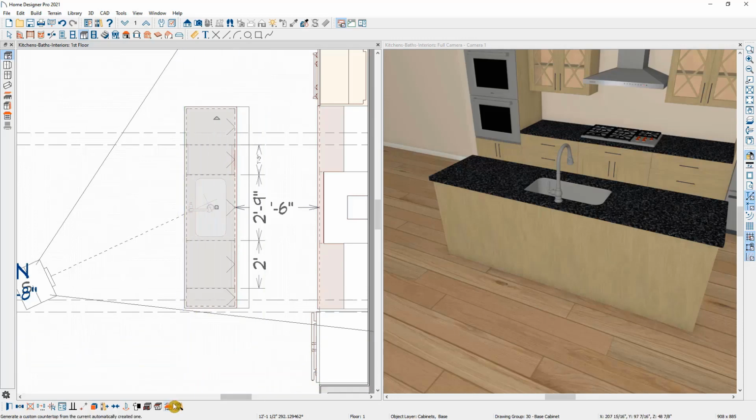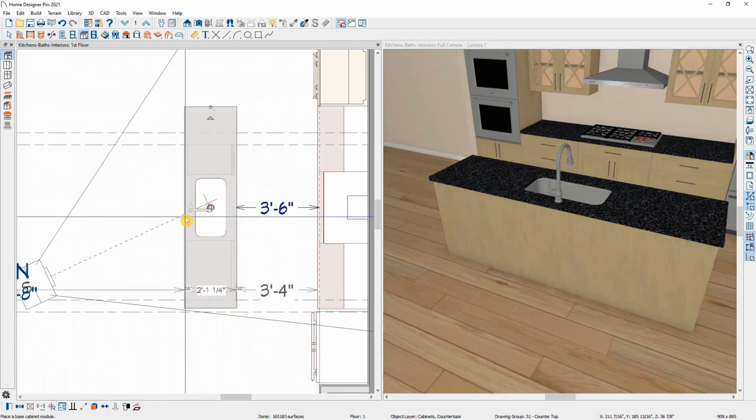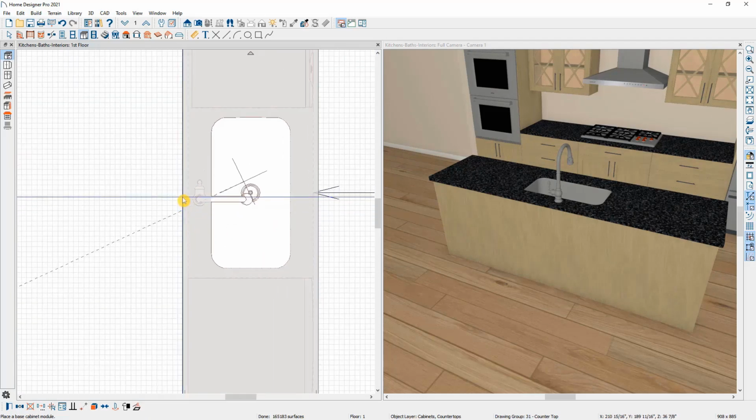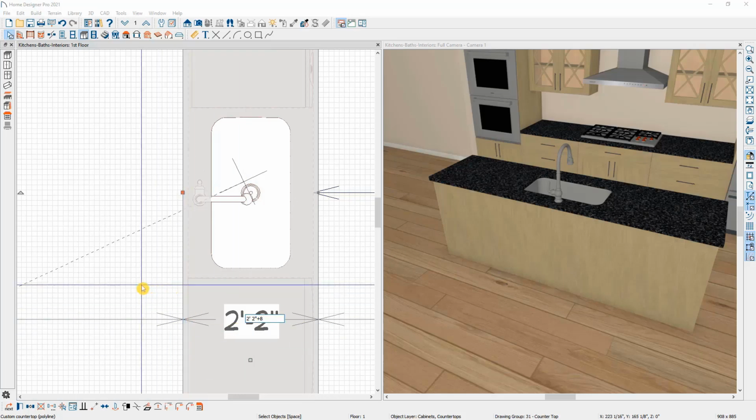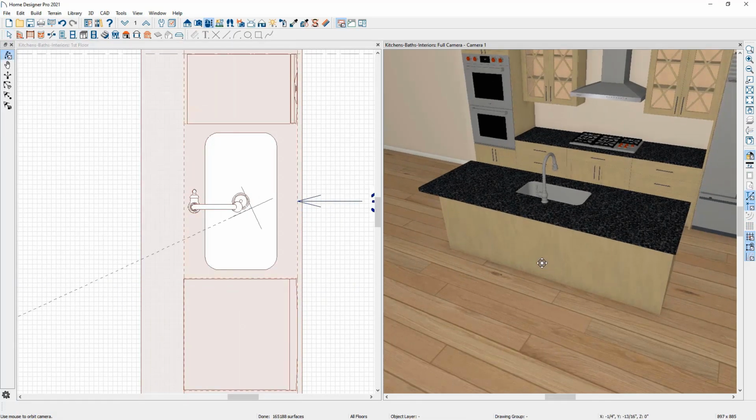And then in the bottom toolbar, I'm going to press that custom countertop option, and that allows us to create a custom countertop in this area. And then I'm going to zoom in and select just the countertop, and you can see the size of it, and I'm going to select it, and then I'm going to add another 8 inches onto it, 1 inch for the existing countertop and another 8 inches to make it extending a total of 9 inches. And there we have that countertop extending.